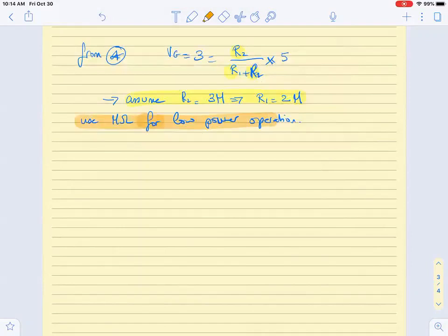If the resistors are in mega ohms, what happens to the current? I have here 2 resistors that are 2 mega and 3 mega, and I have plus 5 volts. Yes, Ali, or who was asking? Yeah. The current will be approximately 0.